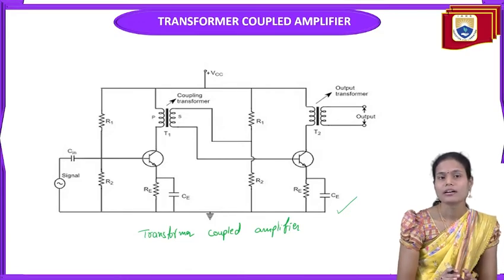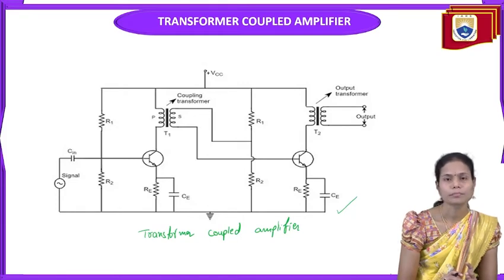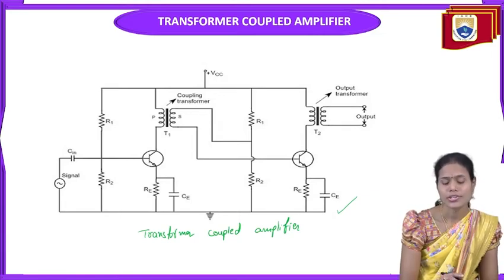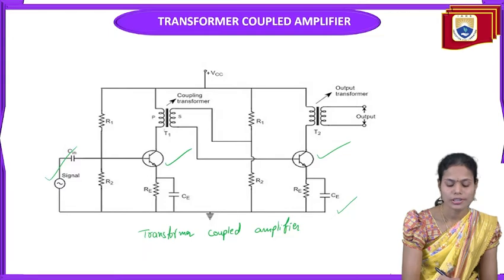So when we want to operate the transistor as an amplifier, we should provide proper biasing through the resistors, operate the transistor in the active region, and set the proper stabilization of the circuit. If we provide these conditions for the two stages of the amplifier, then when we apply our input signal, it is amplified.